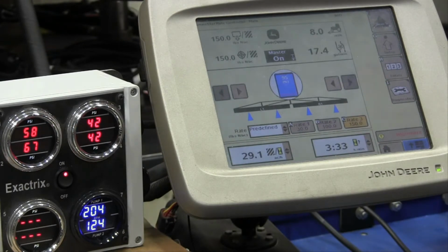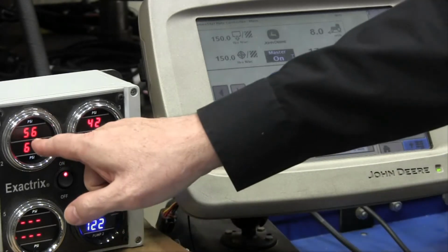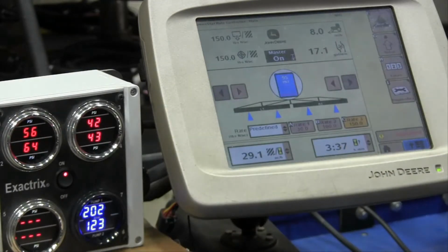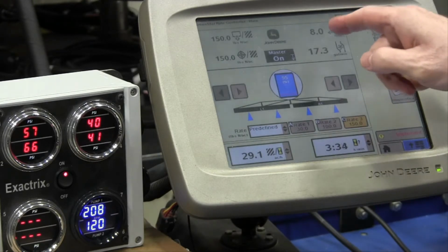Now we'd have some boost on that, wouldn't we, normally, if we were applying NH3? The tank pressure would come in there. So that pressure, if it's 90 psi, would actually be 146 psi. Typically, yeah. So when you use water, this is what we have to do in the testing. But no big deal. All works out just fine when you go to the field. It plugs and plays. So there's 8 mile an hour.